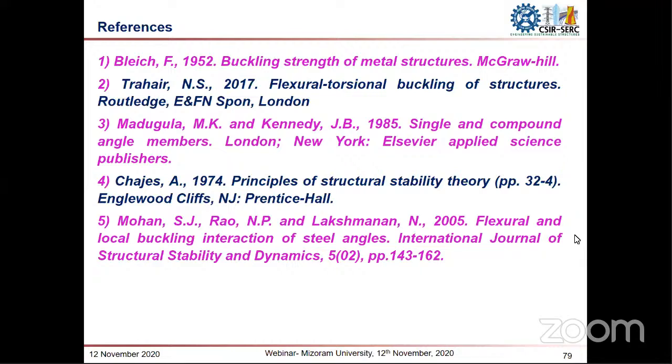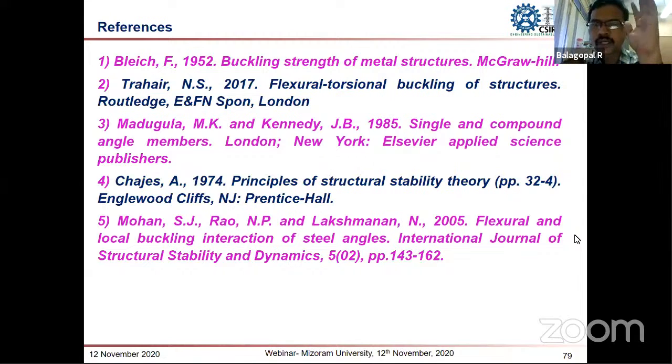Normally, in recent erection of towers, what kind of angle section are they using, sir? Whether you have recommended 60-degree or schifflerized angle based upon your research, or the traditional way? So far in our country, we are using only 90-degree angle sections. Now we are recommending to the Bureau of Indian Standards: why can't we use these 60-degree and schifflerized angle sections for triangular communication towers in our country? That recommendation we are giving based on our R&D results.